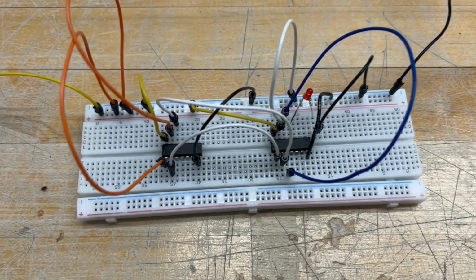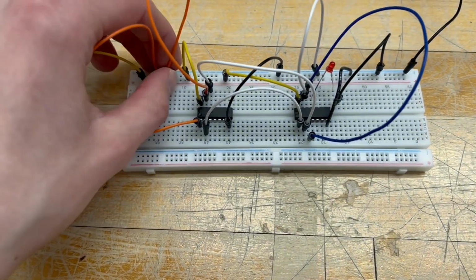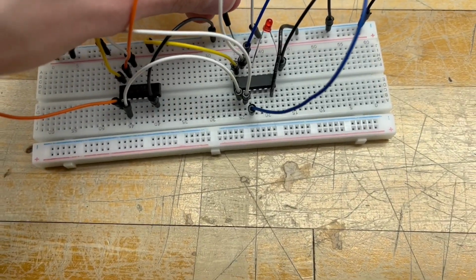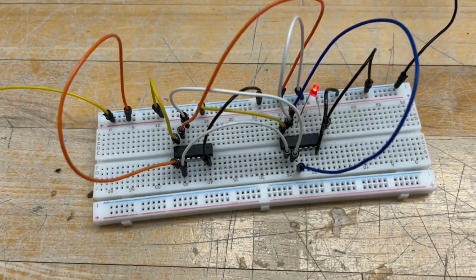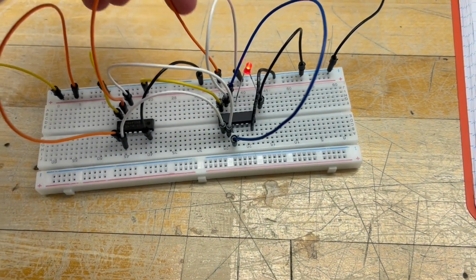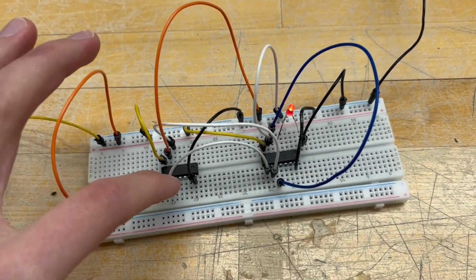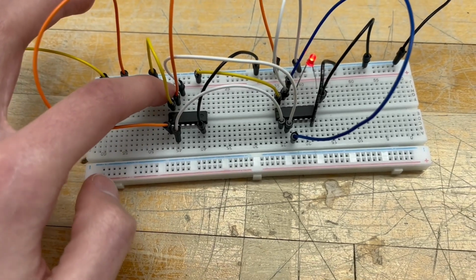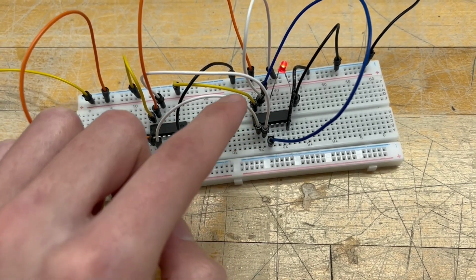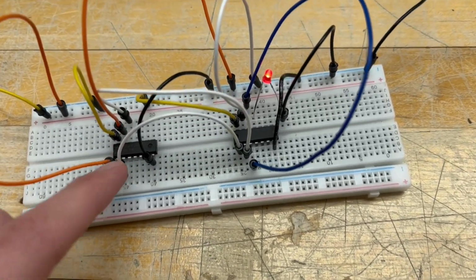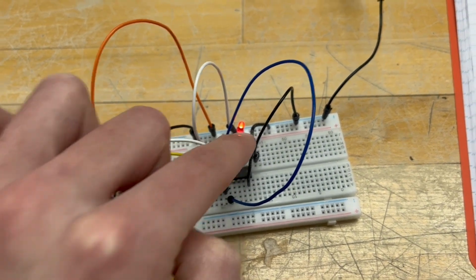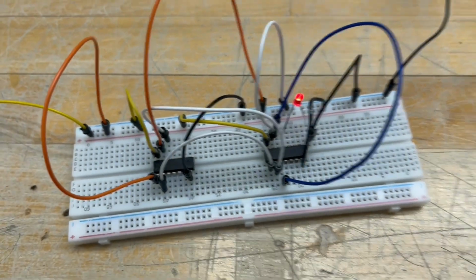But if I were to, let's say, change x, so take x from the 5-volt source and plug it into ground, it will now turn the LED on because x is 0, right? This orange wire right here, 0, and it's being inverted and then turned into 1. So it's 1 plus 0, because z is still 0, plus y, and y is 0. So 1 plus 0 plus 0 is 1, which turns the LED on.